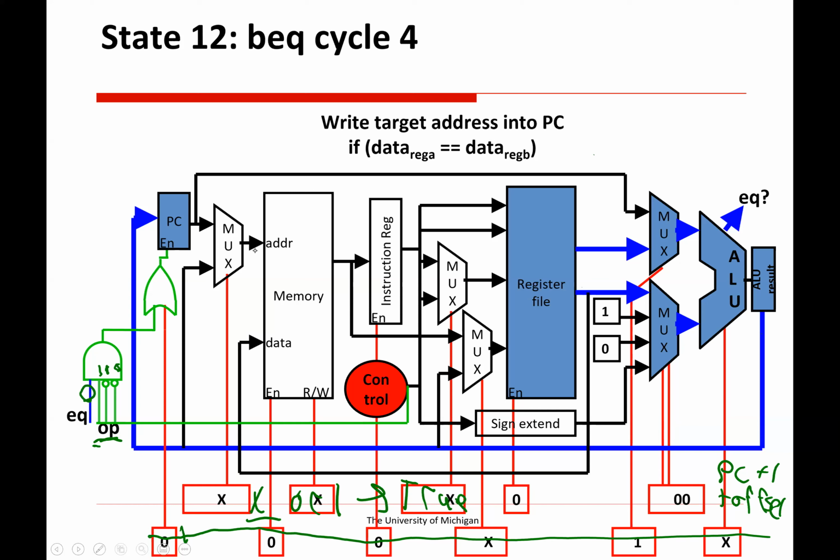If it's a shorter clock period, but we're doing less work overall in each clock period, doesn't that just cancel each other out? Like in particular, the load word instruction is not going to be any faster in this case. It's still going to take the exact same amount of time as before. It's just we're spreading that work across multiple clock cycles. And in fact, it's probably going to take a little bit longer because we're adding in registers in the middle, and that adds delay with the setup and hold times.